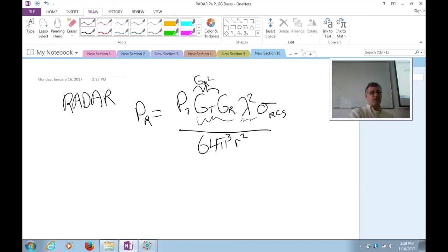And in fact, if this is a GR squared or a GT squared, you're in a monostatic radar link. I know which direction I want to listen to because it's the same direction I transmitted from. So I could get 1 over lambda to the 4th by adding a directional antenna, and that will easily overcome that additional lambda squared loss in the link. So I see some of the same principles at work, right?